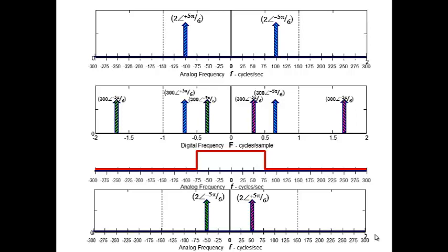There's our continuous time signal: 4 sine of 200 pi t minus pi over 3. Our sampling rate was 150 hertz. So we ask ourselves, what's our analog frequency? And you tell me it is, again, 100 hertz.